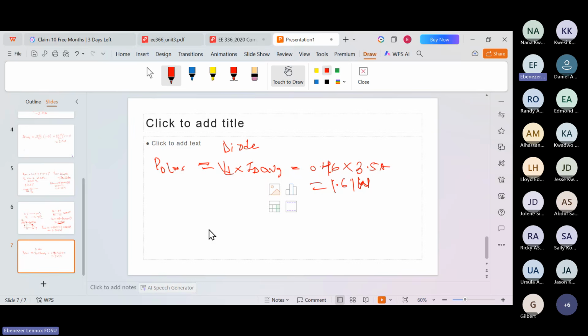The IGBT turn on and turn off energies are 0.04 millijoules and 0.06 millijoules respectively. The diode switching losses are negligible. In constructing the circuit, the IGBT and the diode are physically mounted on the same heatsink.